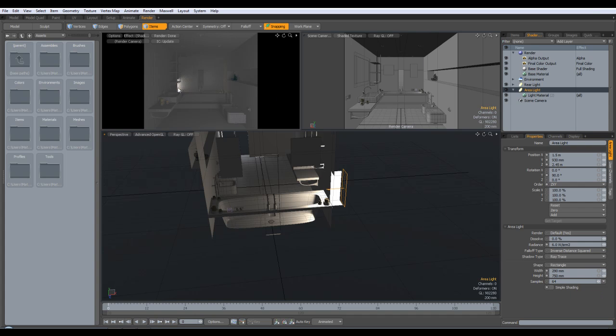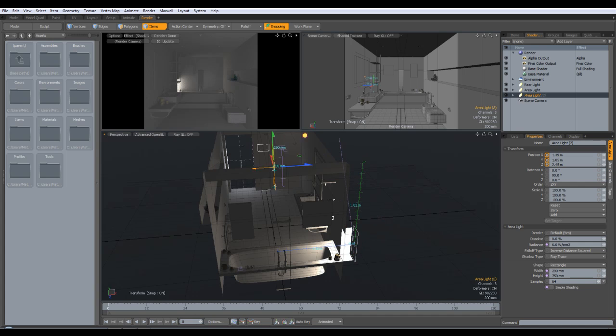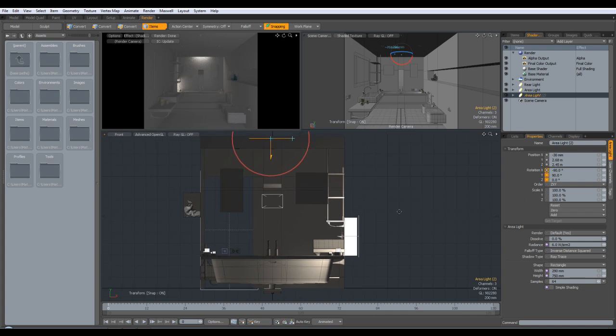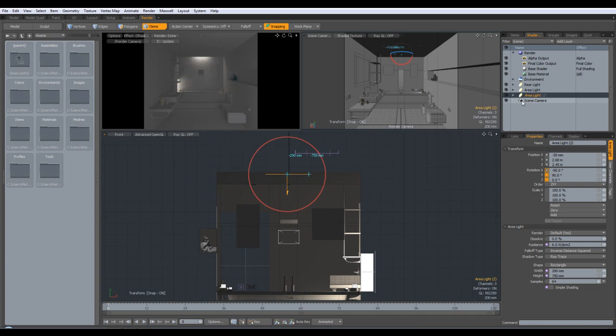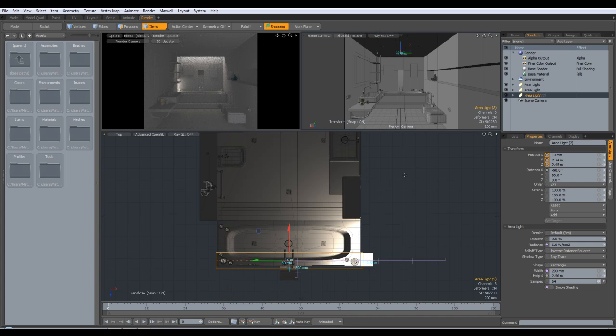Now straight away you can see there is some grain, and that's noise produced by the area lights. Area lights are notorious for being noisy. I'm going to right click on it, and in this case I'm going to send instance. That way, this will be for this one on the top here. I've done it as an instance rather than a new light or a duplicate, just so I can change the value once in the first light, and the italicized version there will automatically be updated accordingly.